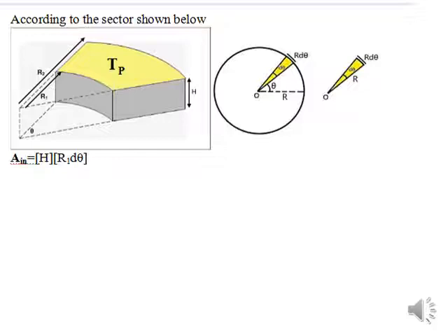From the western side, when you look at TP from the side of TW, you will find that the area for the exchange of heat is the area inner, which is the arc whose length is r1 d theta, and you multiply by h to make this curved area h times r1 d theta. And the area out, when you look from the larger radius and the curved path between TP and TE, you will find that the area out is going to be h times r2 d theta.